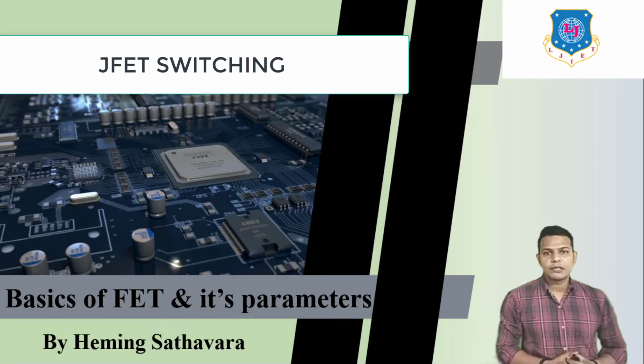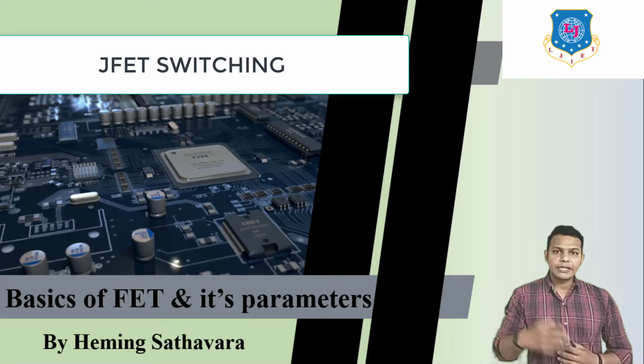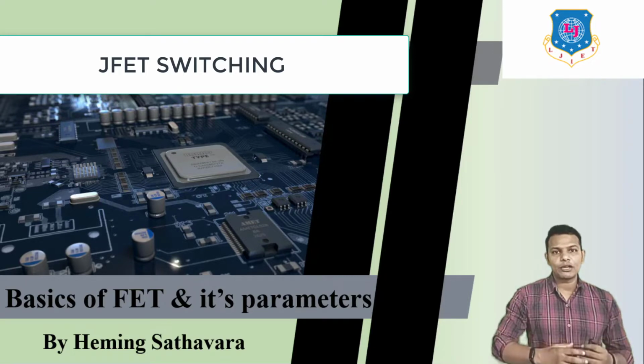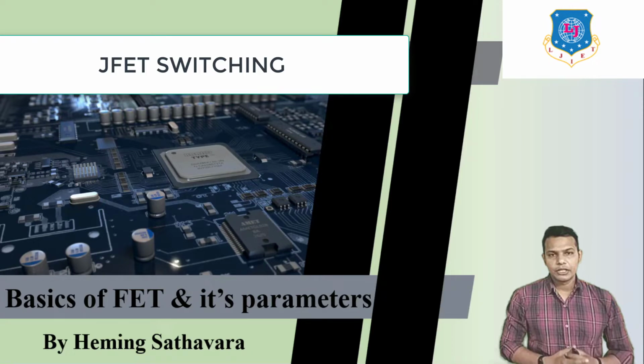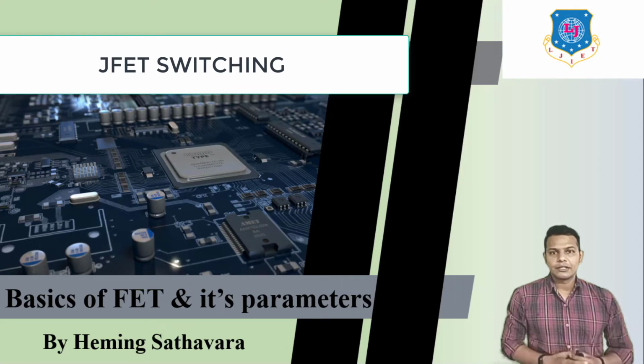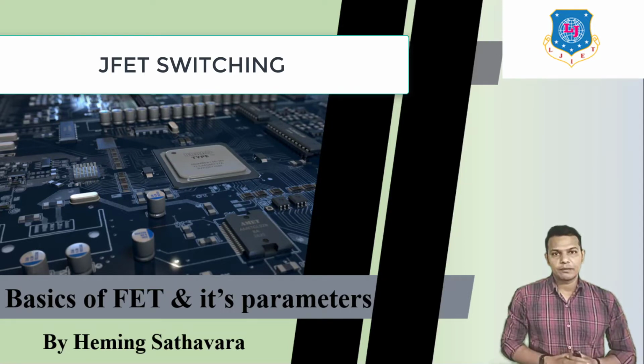Thermal runaway means that if temperature increases, there is an increment of collector current. Due to this collector current increment, power dissipation is generated, and due to this power dissipation, heat is produced, and due to this heat, there is an increment of temperature. So this is basically a chain.